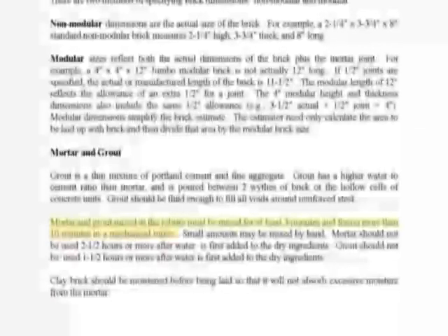Let's take a look at some of the things we want to highlight. In that paragraph that begins, mortar and grout mixed at the job site should be mixed for at least 3 minutes. Let's highlight that. That's a question ready to be asked. And for no more than 10 minutes in a mechanical mixture. Again, let's just continue with our highlighting on that.